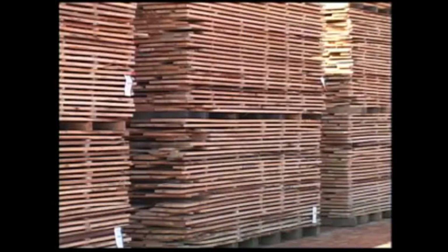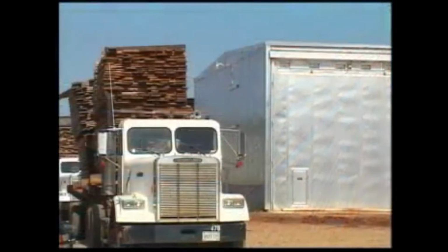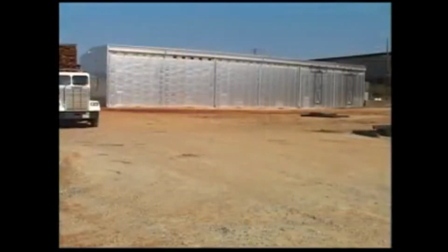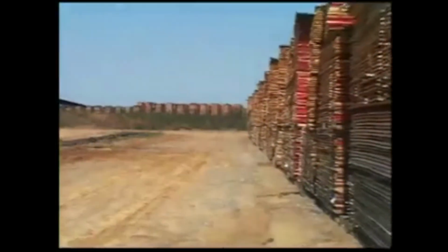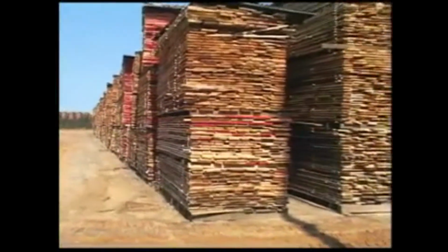The slabs are stacked for air drying at least 3 to 4 months before entering a large fan shed. The fan shed will force air around the slabs, further reducing the moisture levels. They are then stacked into a steam-heated kiln to reduce the moisture to an ideal 7 to 8% level. Accelerating the drying process or rapid changes in moisture loss will cause the wood to split, twist, warp, or curl.